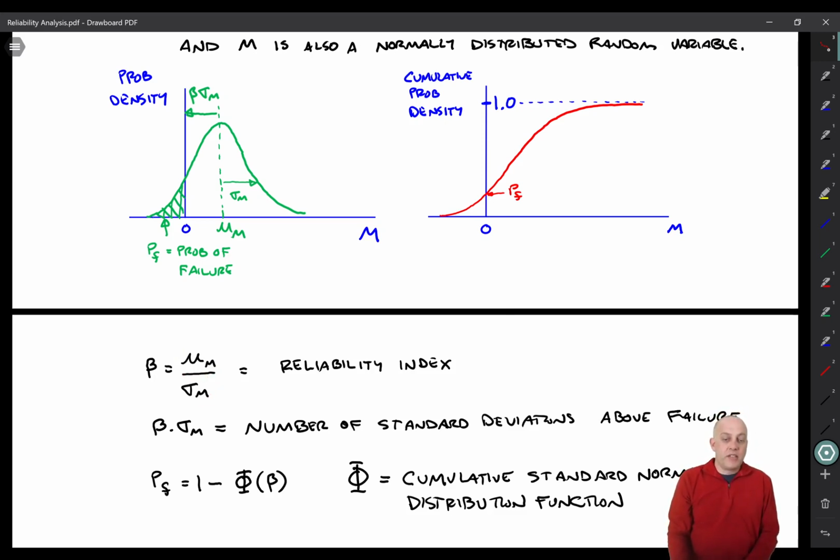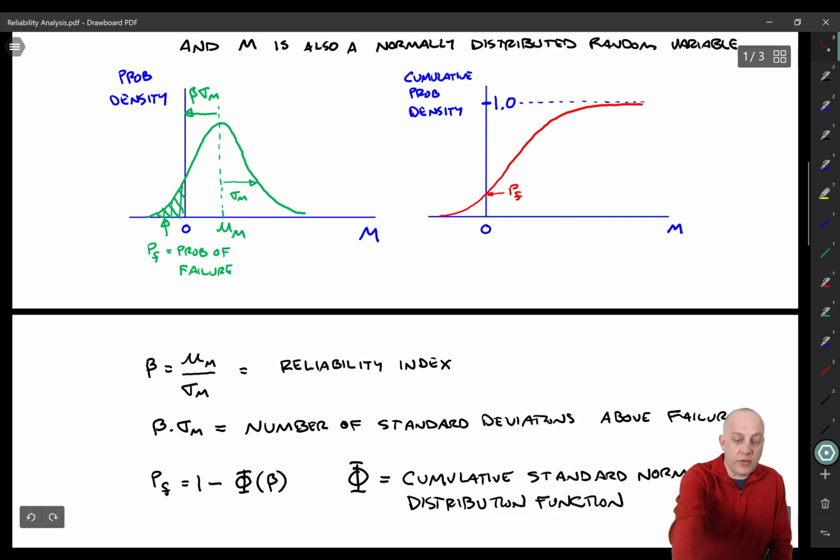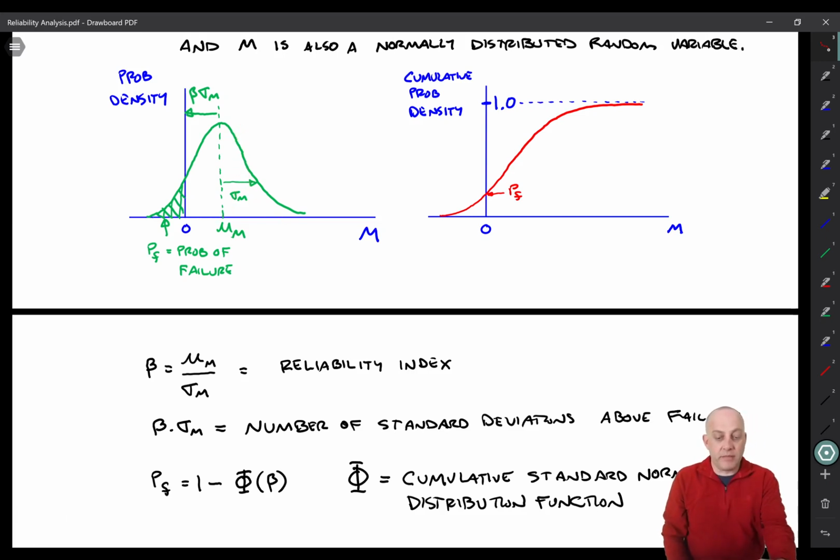And sometimes the standard deviation arises from lack of information. We don't have enough data, and we don't think we know undrained strength very well. So as you know, from a Bayesian perspective, we assign a big standard deviation to undrained strength. We could reduce it by getting more information. So that's another thing you can do. You can get a steeper distribution function, and it'll increase beta.